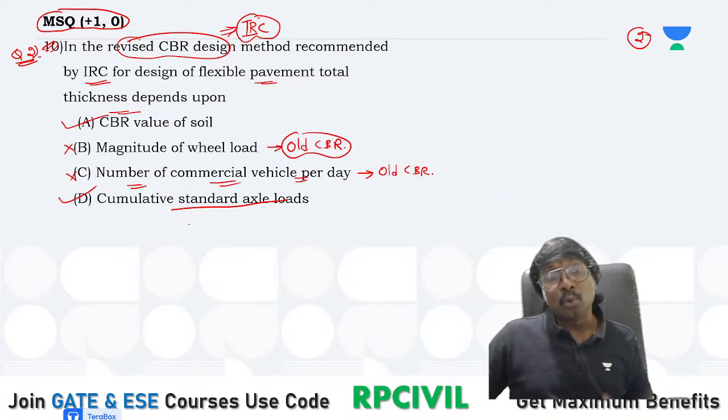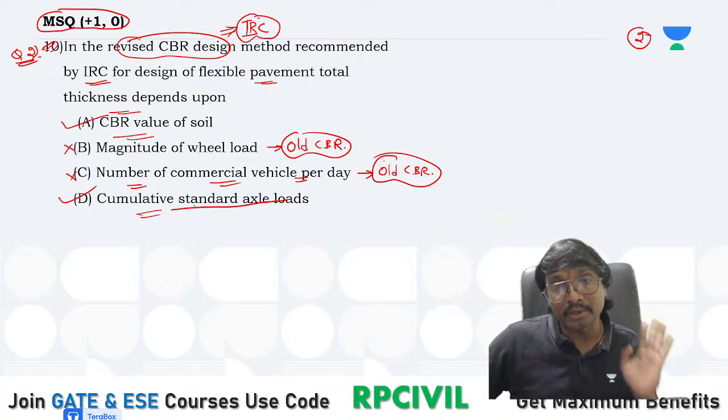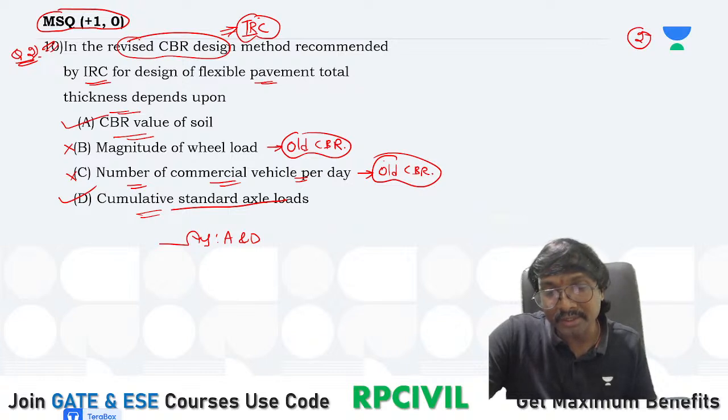In the old CBR method, magnitude of wheel load will come and all will come. Okay, sorry. CBR of soil, magnitude of wheel load, number of commercial vehicles per day, A, B, C will come as per the old CBR method. But as per the new CBR method, only the CBR of the soil and the cumulative standard axles will come into picture. So which one is the correct answer now? A and D are the correct options, if you just observe.